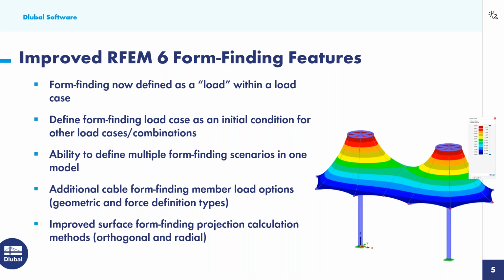Additionally, what we can do is define this form finding load case as an initial condition for other load cases. So we're talking about live load, wind load, snow load, and load combinations, where we combine all of these load cases into the various combinations.